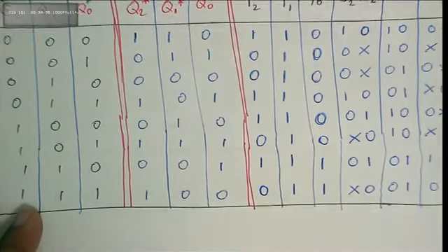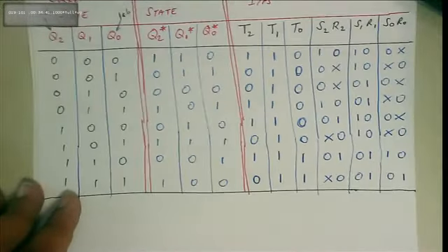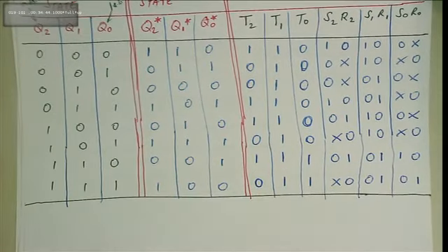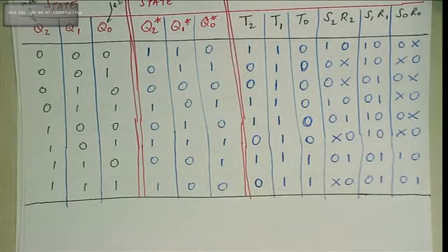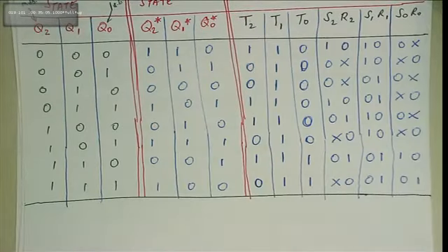The first difference was you have over here, on the left hand side, input X, which controls your forward and reverse direction. Obviously if you have 0 over here, it'll be going in the forward direction. If you have 1, you have to look at your particular state diagram to see what the new values for your next state are.